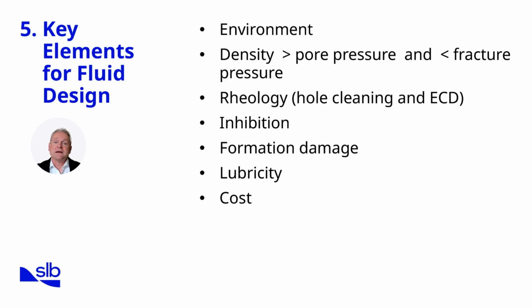Drilling fluids play a central role in both safety and performance. The first factor is the environment. Fluids must be compatible with temperature, pressure, and chemical conditions in the well. The fluid density must remain greater than the pore pressure to prevent influx, but less than the fracture pressure to avoid losses. This narrow drilling window often defines the operational margin.